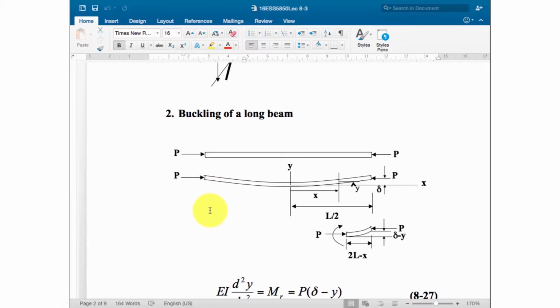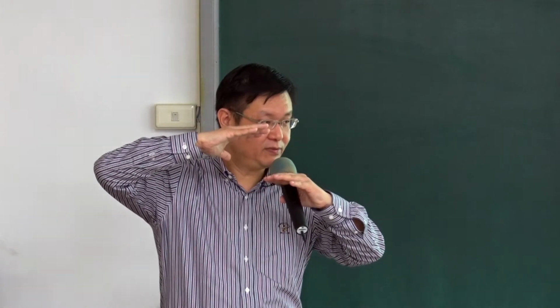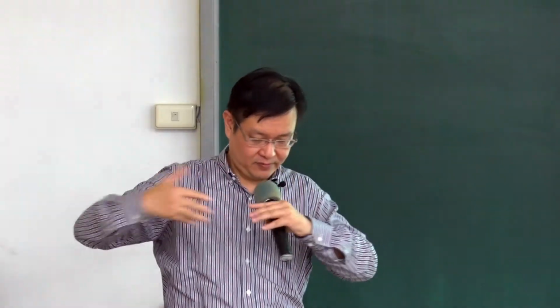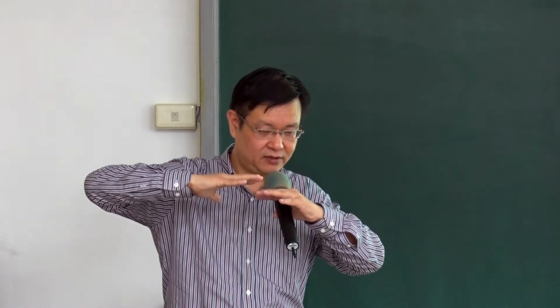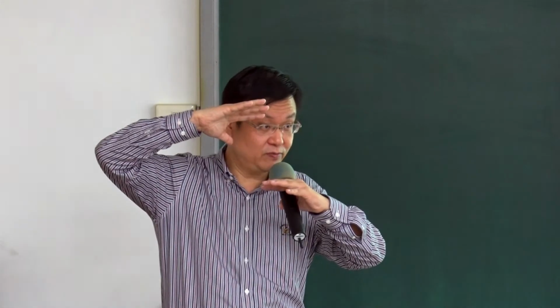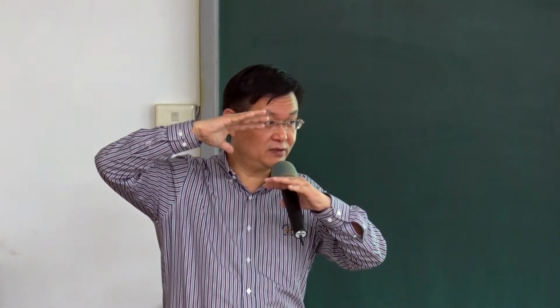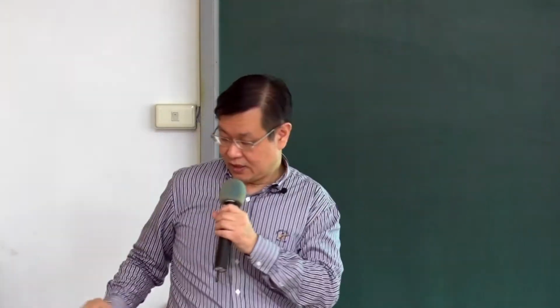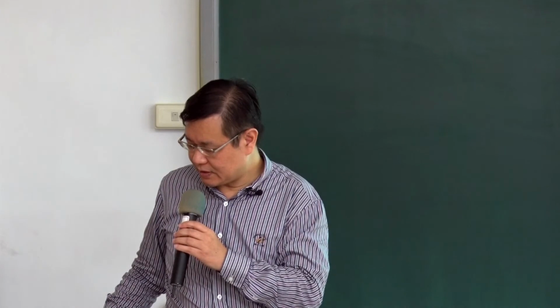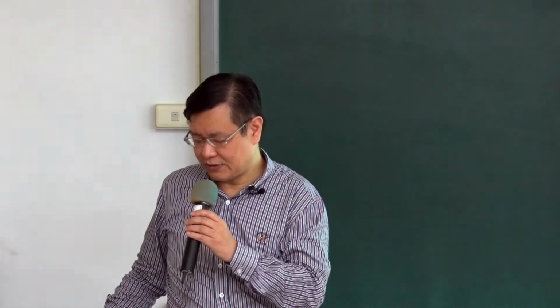The overlap of the fingers will become non-overlap. If you push the whole center part of the actuator above the surface too much, that's a problem, so the system will fail. The situation comes from the buckling. The buckling sometimes is not from the electrostatic force, because the electrostatic force is usually very small. It comes from the fabrication.